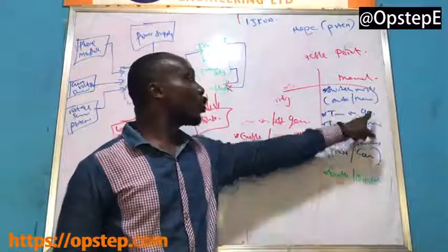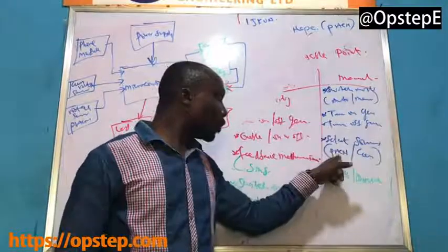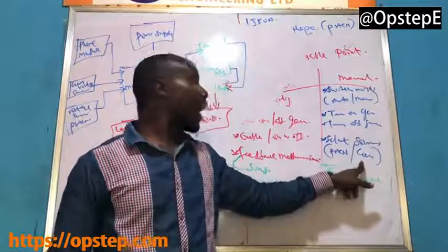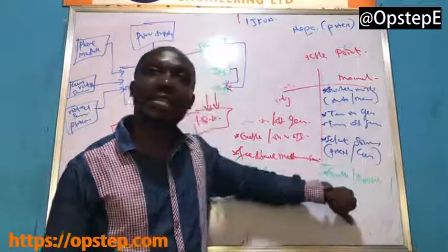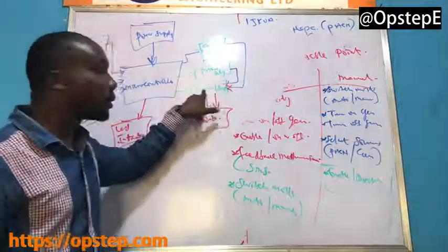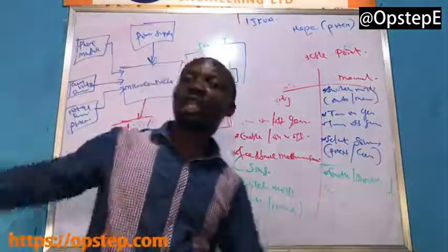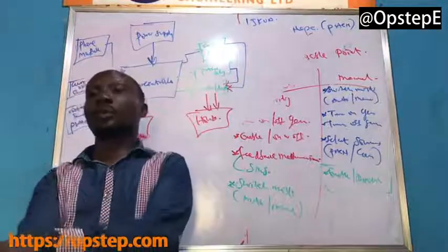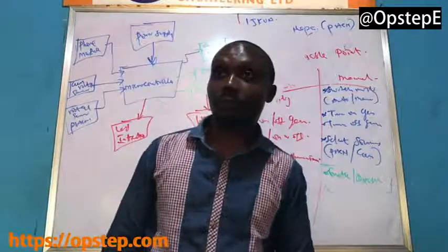Now, even if you turn on the generator and select generator as the source, and you forget to enable it, the generator will be running, of course, you know the generator is running, but you have gone inside and crossed your legs on your bed waiting for light. The light isn't going to come.